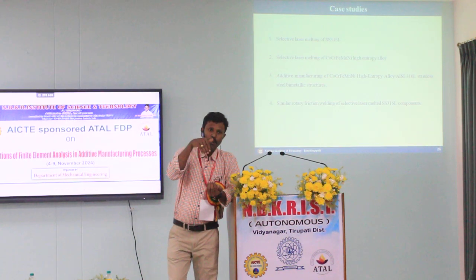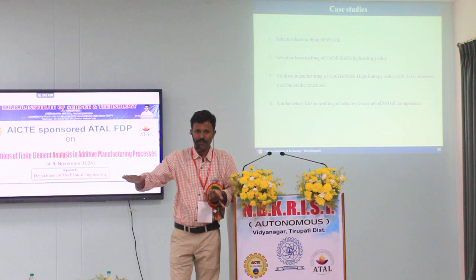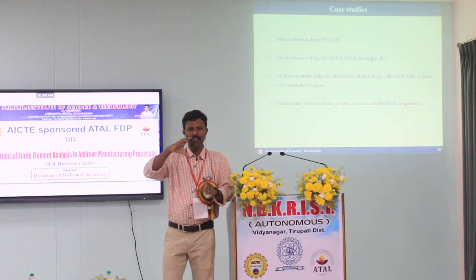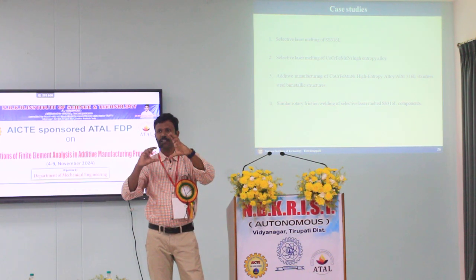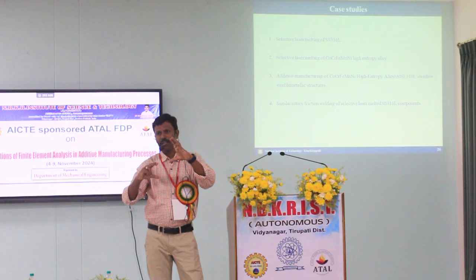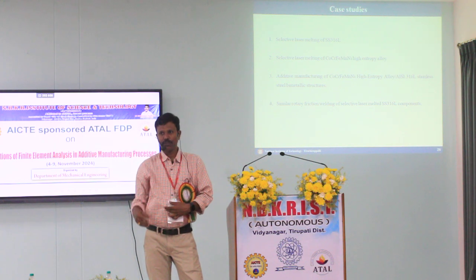Paired with that of bimetals. That means first, the powder bed we will make with, say, 316L, build it, then drain the powder, add Inconel 718 powder, and from there build Inconel 718. So one cylinder we get has bottom 316, top Inconel, bottom 316, top high Inconel, bottom Inconel 718, top high Inconel. It's a single piece like that.